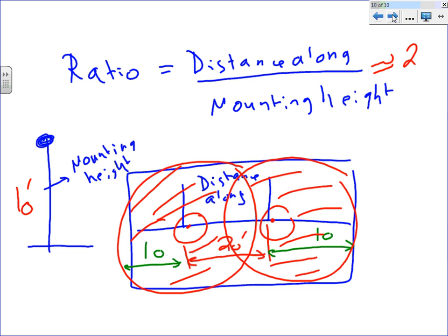The good news is, Visual lets you calculate at any angle. When you choose, they call it the calculation zone. So where do you want to put your calculation zone? You can put it horizontal, or you can grab this wall and make this wall your calculation zone. When you run the analysis, it will give you the foot-candles at this wall. The default is every 2 feet. They grid the whole wall 2 feet by 2 feet, and at every intersection it gives you a calculation vertically.